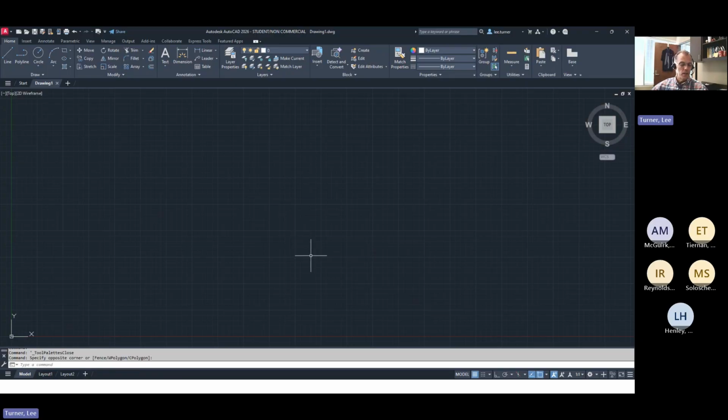If you've done any of that, you've updated the workspace. And so if you want to keep those settings, then you need to save a workspace. Let's save one together first. I'm going to move my mouse to the bottom right-hand corner down here at the drawing aids and find the little gear. If you hover long enough, it'll say workspace switching. If you click on the arrow next to it, you'll see that we're in drafting and annotation. We're about to switch to the 3D modeling in a minute, but before you do, save a new workspace with any of your settings.